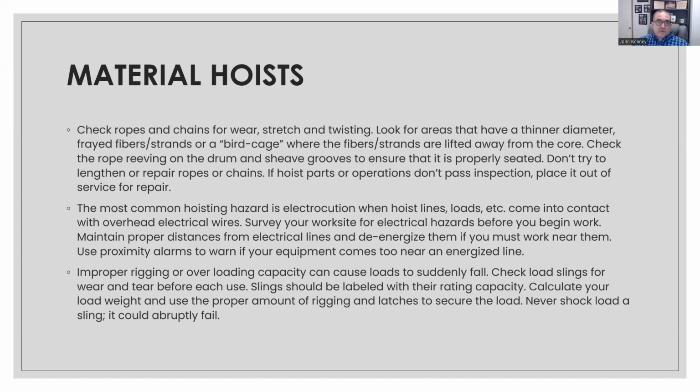So if you're using a roof hoist or any other power hoist, whatever that may be, and you're operating it, you're still required to go through checking all of these. And again, I stress having a checklist together so that at the end of the day you always have a record that all this has been done, and it becomes part of your daily job record.